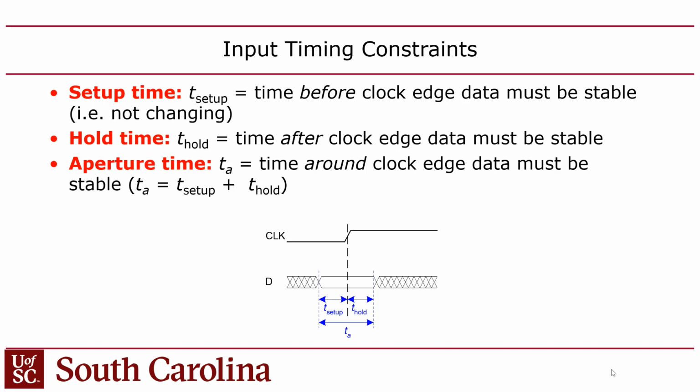Yes? Is there a way to define the setup time and hold time based on how gates are connected to the flip-flop? Yeah, it's all technology dependent. It depends not only on the design of the flip-flop, but also on the semiconductor technology. So this is one of those things that's going to improve with Moore's law, basically. But it's a function of the underlying technology. So unless you're in the fab, fabbing chips, you basically don't have any control over this. You have to take these numbers from the spec sheet, the technology sheets, or the data sheet, and go with it.